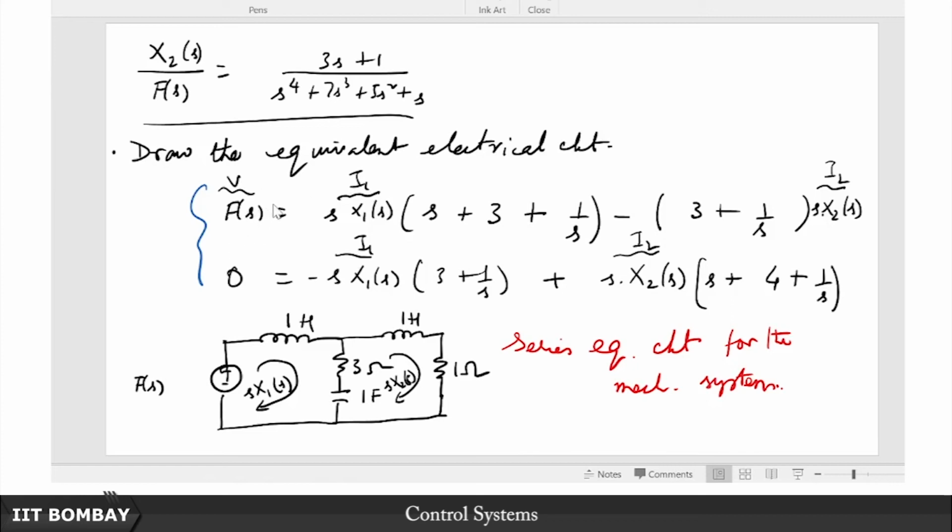Recall, we had said that it is the sum total of all admittances of all those branches which are incident at node 1. By the same token, what is the coefficient of V2 in the equation for node 2? It is the sum total of all the admittances of all the branches that are incident at node 2. Very similar, isn't it? Give it a moment's thought. What about the cross terms? In other words, what is the coefficient of voltage 2 in the equation for node 1? It is precisely the admittance that is common, or shared between node 1 and node 2. What does that mean?